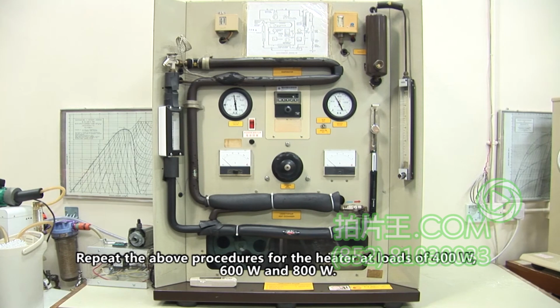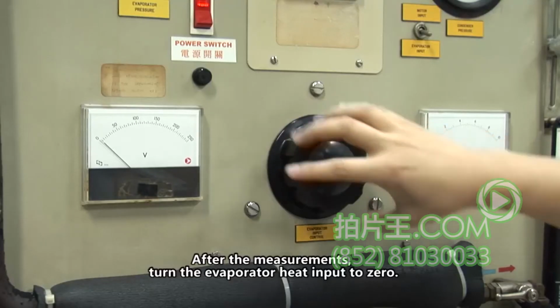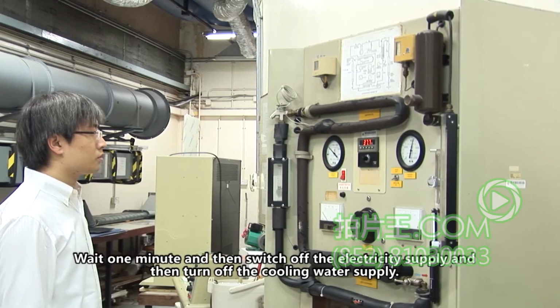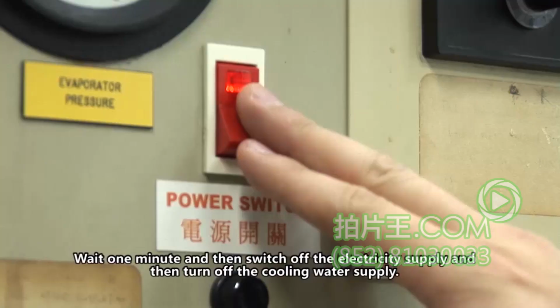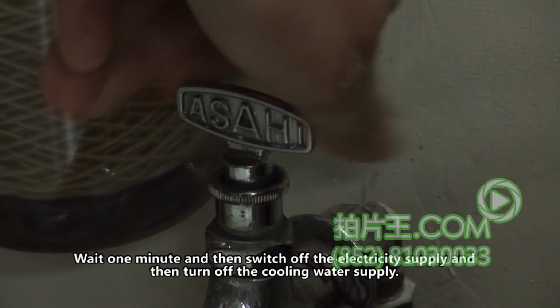Repeat the above procedures for the heater at loads of 400 watts, 600 watts, and 800 watts. After the measurements, turn the evaporator heat input to 0. Wait 1 minute and then switch off the electricity supply and then turn off the cooling water supply.